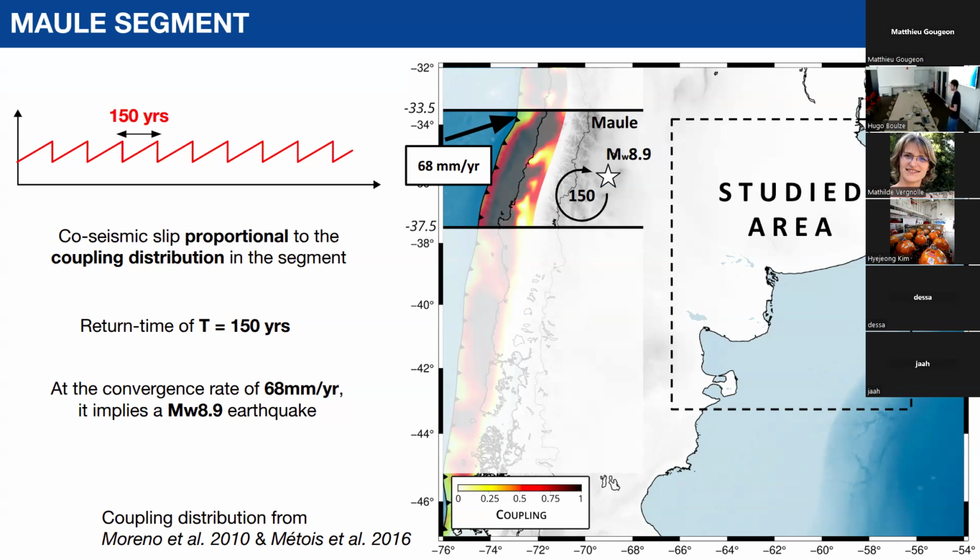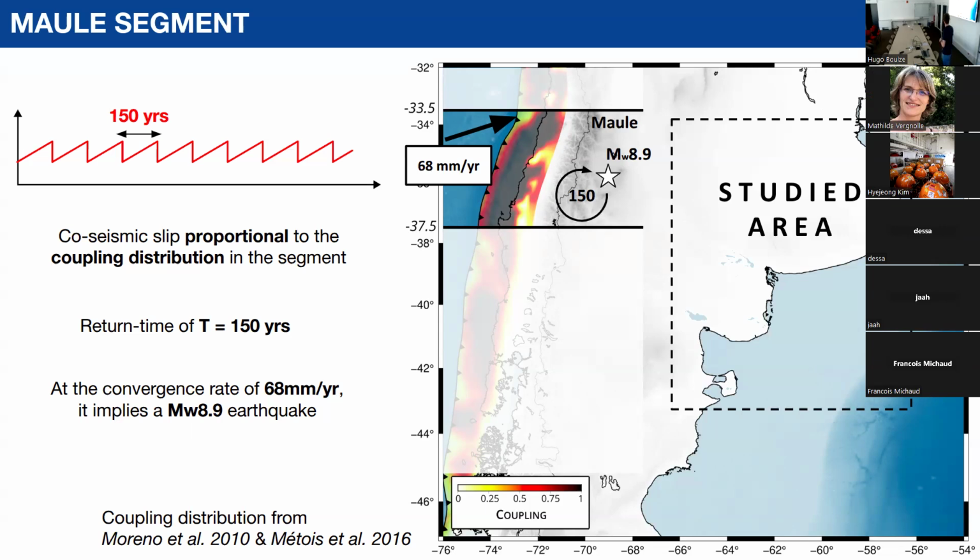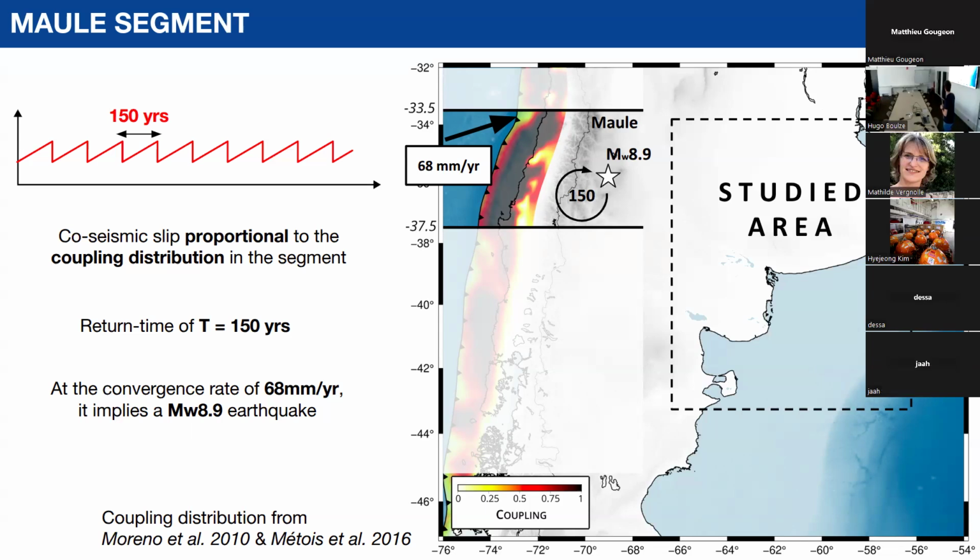That is the key actually of what I am showing you today, rather than having a really good fit in the near or in the midfield. But afterslip can also have an impact on far field deformation, because it's a slip on the interface, like the earthquakes, and it induces also its own viscoelastic relaxation. So it could be interesting to look at it a bit more. Yes. Yeah, it would also change your transient viscosity, actually, not only the steady state one, I suppose.